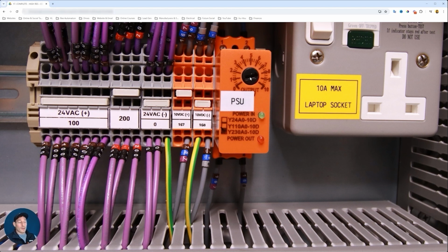Now, what we could do is perhaps if someone puts the boiler into hand, we don't necessarily, when it's in manual mode, want the boilers to be firing up at full power, giving out 90 degree heat, which might not be a good idea, might not be necessary. It's going to burn a lot of fuel.